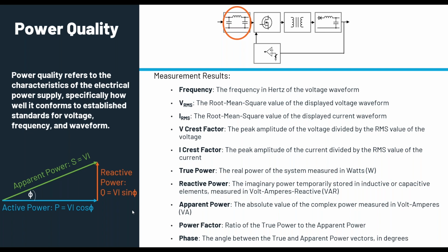So you will actually have an active power, which is the power delivered to the load, and there'll be something called reactive power, which doesn't get delivered to the load, but keeps oscillating between the power supply, I mean the input side, and the reactive components like capacitors and inductors. And so we want to reduce that part. And so the apparent power is nothing but how much the power dissipation looks like. So that's the resultant of both of these.